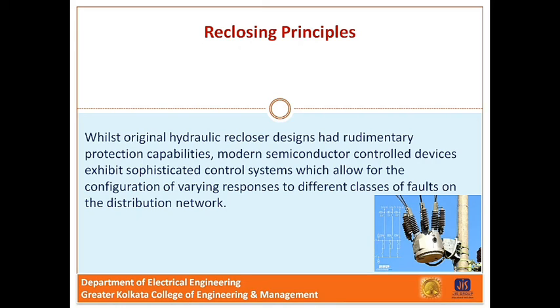Recloser can then apply a fuse burning policy where they remain closed for a short period to allow fuses on lateral lines to burn, isolating the fault. If the fault is not cleared, the recloser trips open again. This policy can be used to deliver energy to fault sites to burn the fault off the line. This could be a branch crossing between multiple lines or coming into contact with the conductors.